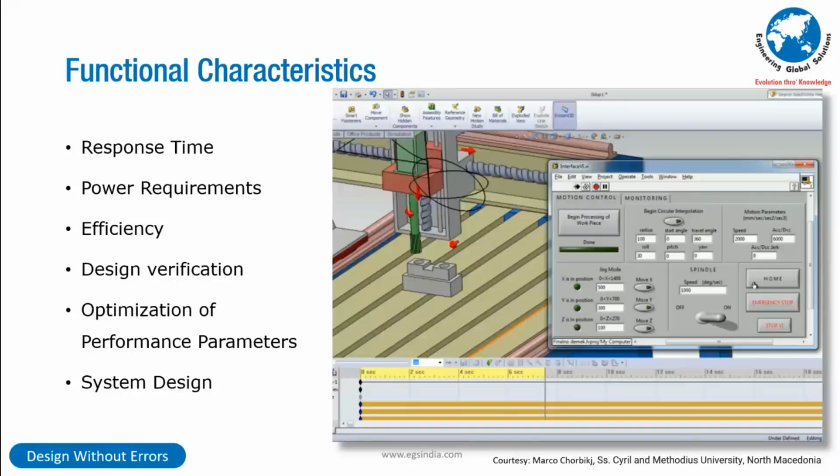This one in particular is the NI tool, LabVIEW, where you can actuate it from inside the LabVIEW interface, and you can see, go through the motions inside your SolidWorks. Some of our customers are using it. The advantage of this is your response time calculations, your power requirements, your power fluctuations, the torque pulsations, the efficiency calculation can be verified at the design stage itself, and it gives you the scope for optimization.